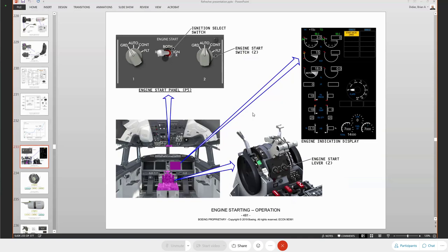Okay, well, what you can do also is bring up your air supply data page that has that more accurate indication and put it on the display on your OMF, so you have everything right there next to each other. You can keep an eye on the engine and you have the air pressure right there next to you also. Okay, it makes life a little bit easier.